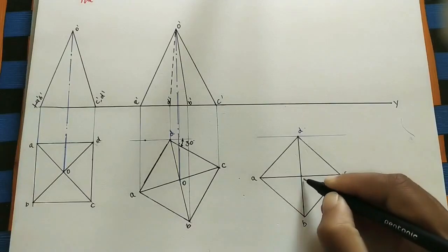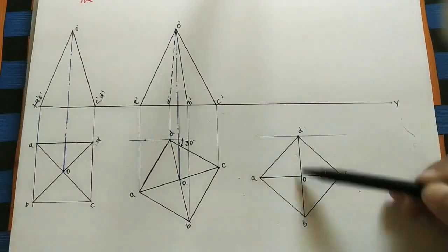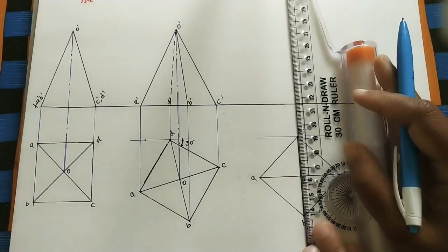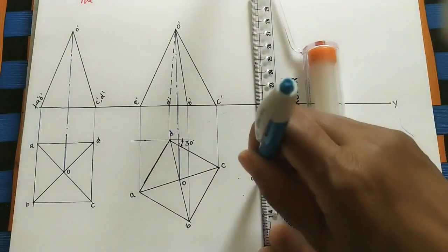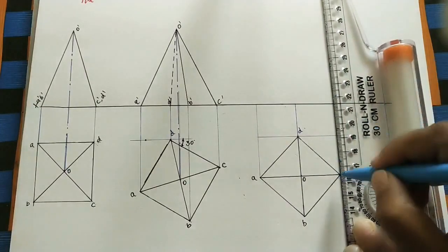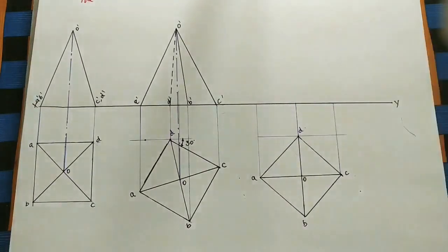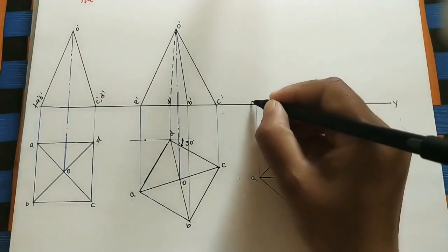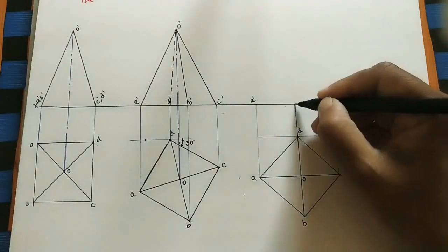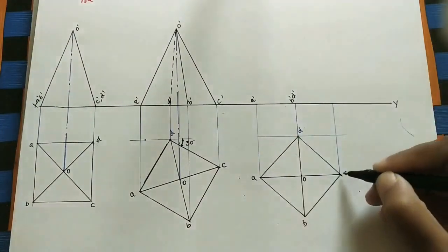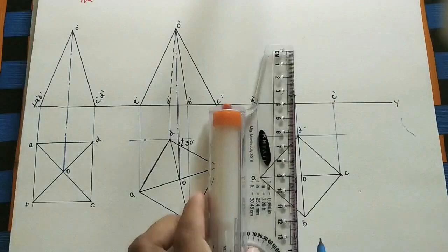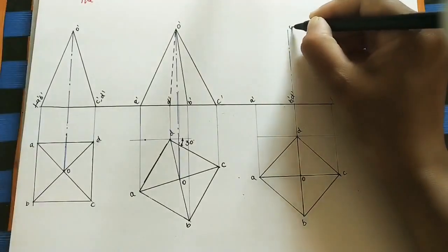So this is the apex. After doing the top view, do the projector lines from all the corners. Take this as the reference. As we know, this is a vertical line. Mark the front view points. A point is A dash. Here B, D and apex are coming on the same line. B and D coming here, B dash, D dash, here C dash. After marking these points, take axis length 6 centimeters. Okay, above XY. This point is the apex.